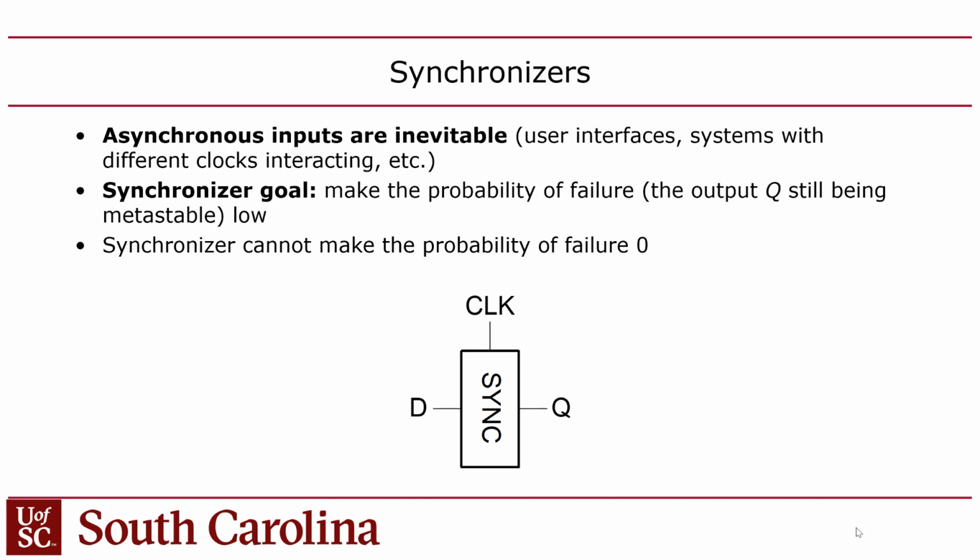Point this out. Where we're going with this is we're going to add a synchronizer. We want to add an extra flip-flop between the flip-flop that we normally want to use to capture the input and the switch, the button, right? You add an extra flip-flop, and then all we have to calculate is two things. We need to know the probability that the first flip-flop, the synchronizer, will become metastable, because it's sacrificial, basically. If that first flip-flop goes metastable, as long as it resolves itself in the whole clock cycle it has from that time to the actual golden flip-flop, which is the one that we actually want to sample into our design, then we're fine. Now, what happens if it doesn't? If it doesn't, we've got a problem. It's going to fail. But at least we can calculate the mean time between failures, and that's what we're trying to do with this, right?